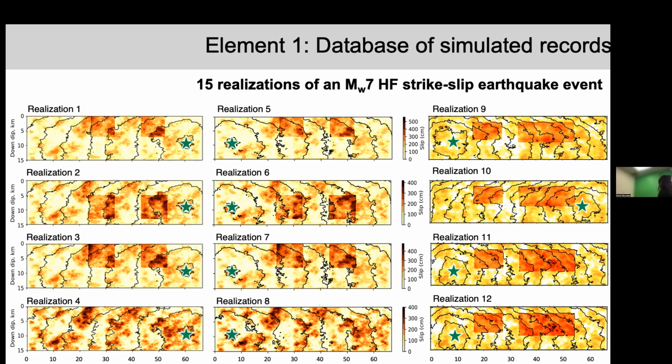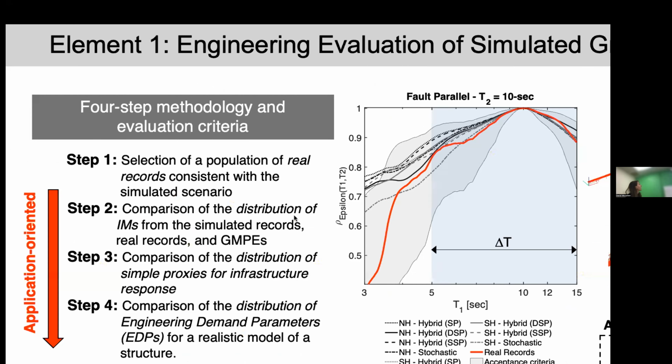All these models share the same frequency resolution, which is 5 Hertz, the cap on the shear wave velocity, 500 meters per second, and they all utilize the USGS 3D model for the representation of the geology structure with topography. And so here, starting within this core element number 1, we have developed and proposed, let's see if I can advance this. Okay,